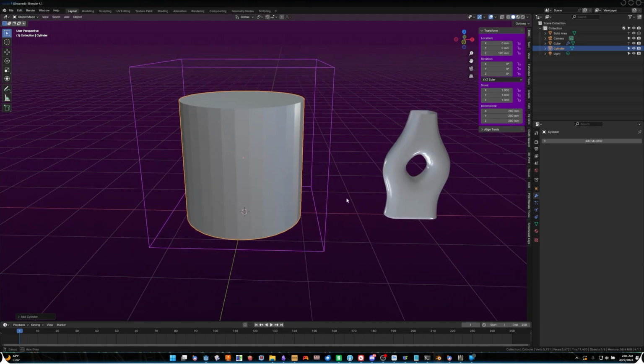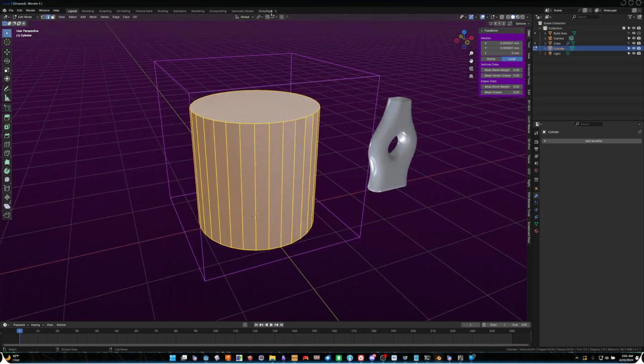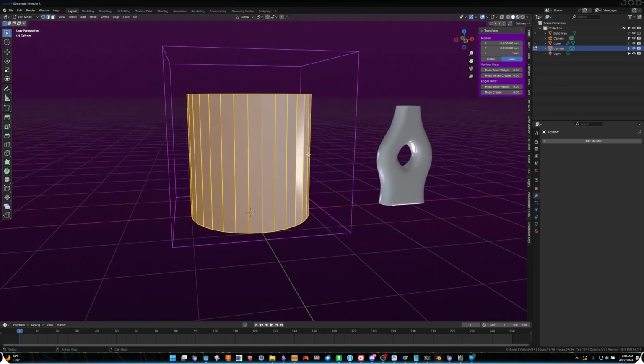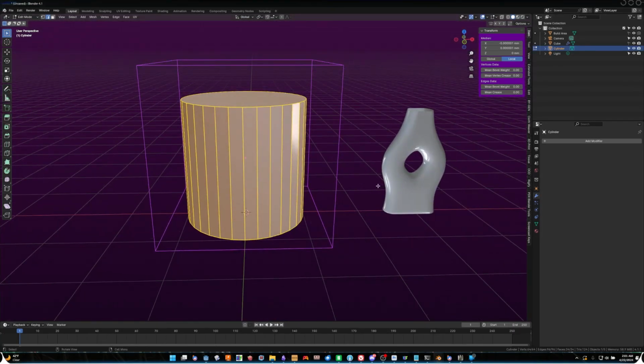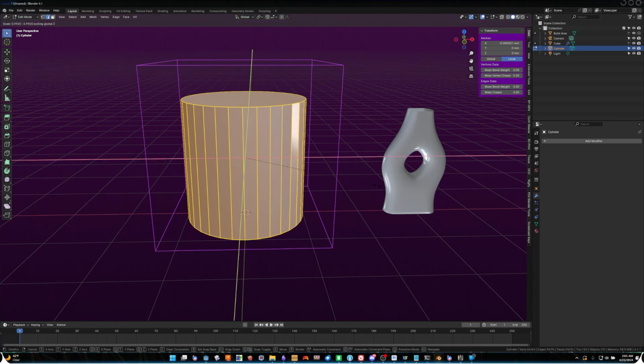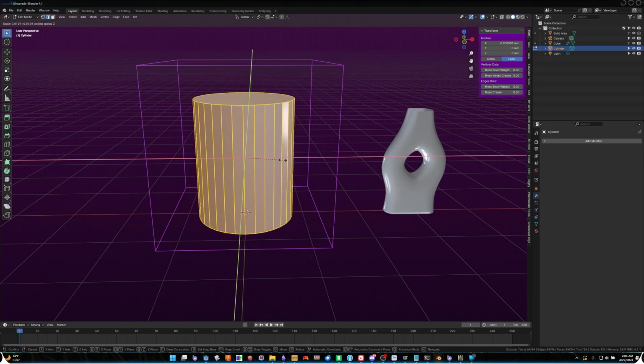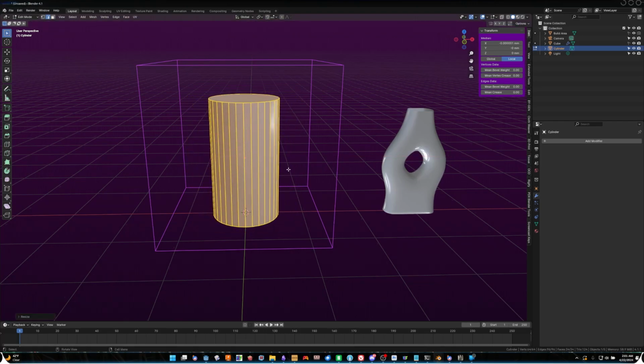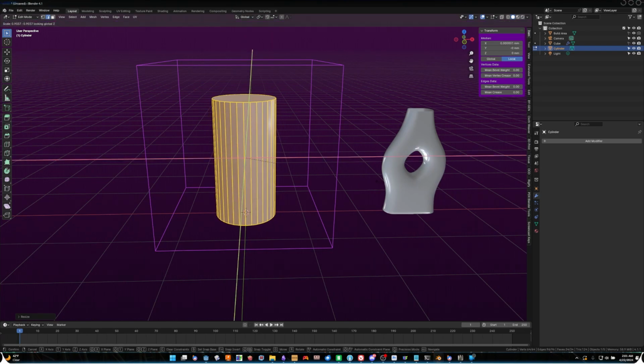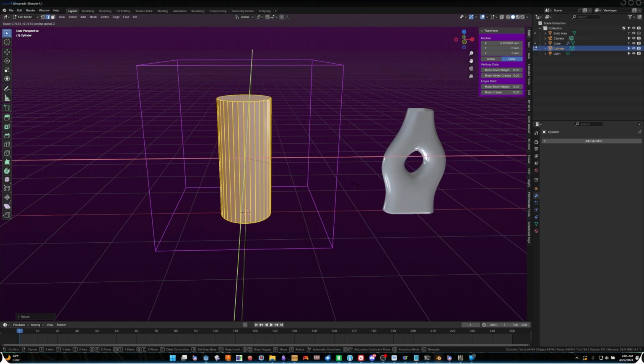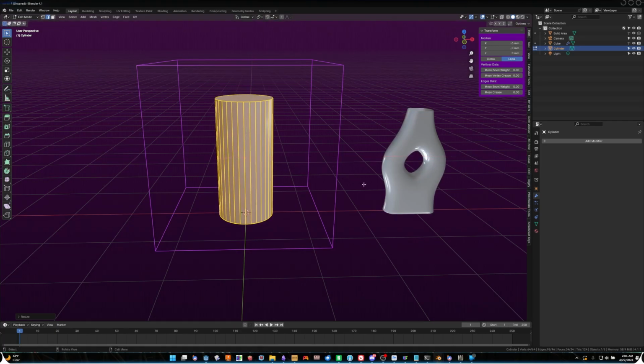And I'm going to show you how to scale. I'm not going to use the transform pivot point again. What I'm going to do instead is hit S, hold Shift, hit X, and then hit Z, and then release Shift. It looks like I need to do that one more time. So I'm just going to hit S, Shift, X, Z, let go of Shift, and now I can actually scale it faster. And that looks pretty good.